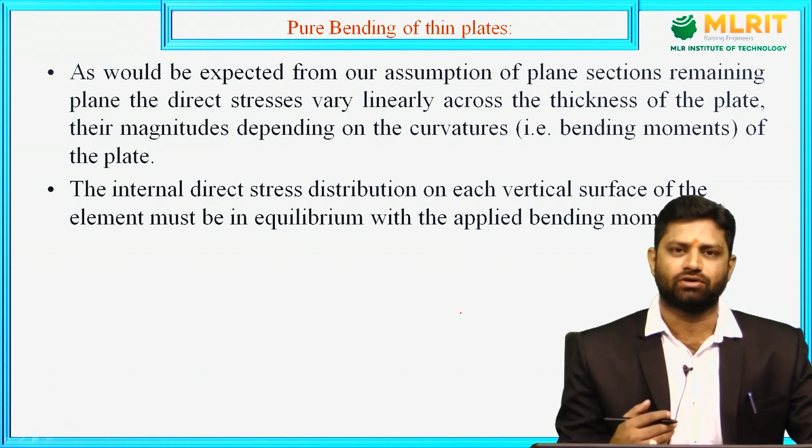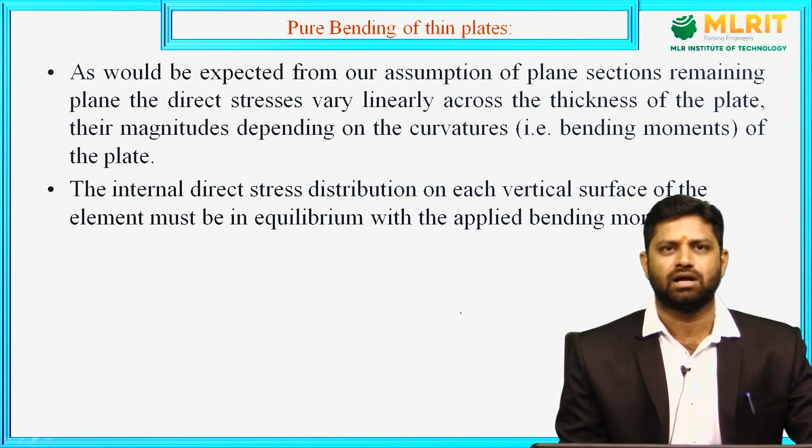In other words, their magnitudes depend on the bending moments of the plate. Now we have an equilibrium condition. Since we are applying bending moments mx, my, stresses sigma x and sigma y are going to be induced, so we'll have an equilibrium relationship between these two.